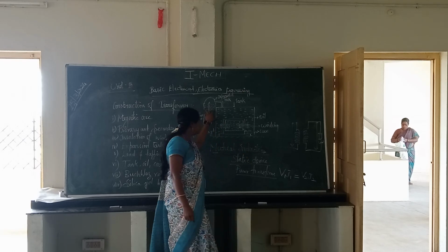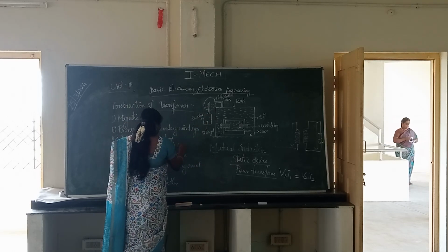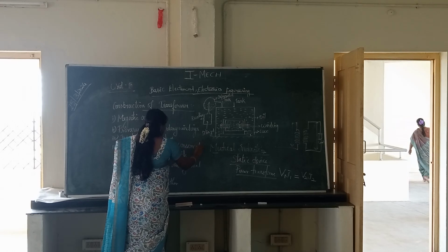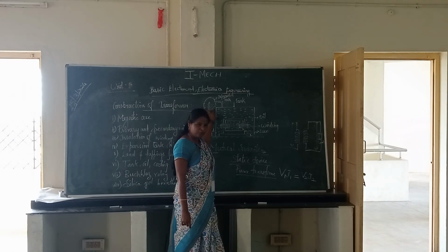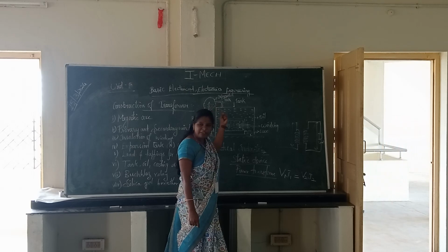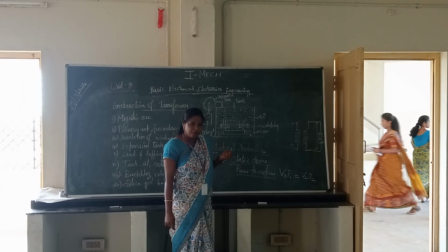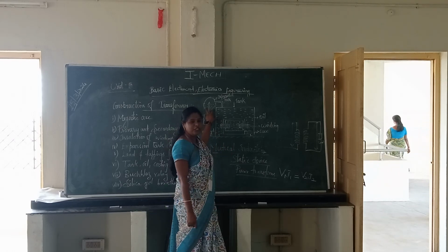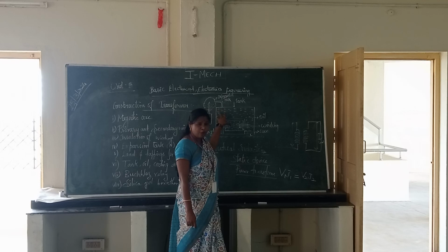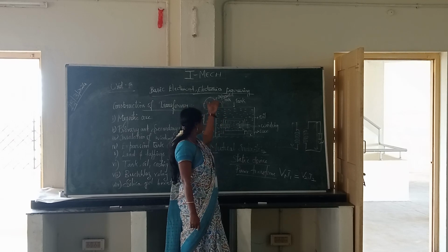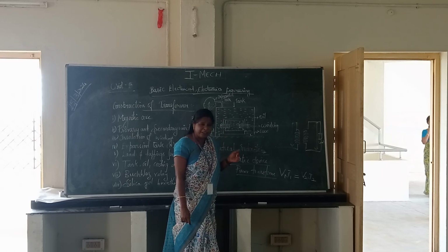And we do have an extra expansion tank, which is also called a conservator. Expansion tank is also called the conservator of the transformer. Okay, which will contain some oil. As days pass, heat is generating too much and the oil will drain out. So the expansion tank is also filled with oil so that it takes care that the transformer tank is always full. The oil in the transformer tank does not get reduced. If the oil in the tank reduces, oil from the expansion tank will come to the transformer tank. Okay, that is why it is known as extra oil kept in the expansion tank.